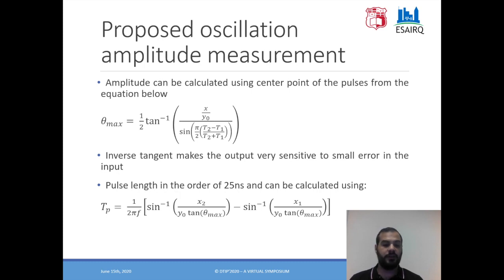This means that a photodiode with adequate rise time and fall time is needed. It is also important to note that the rise time and fall time do not depend only on the photodiode specification, but are also dependent on the laser spot shape.